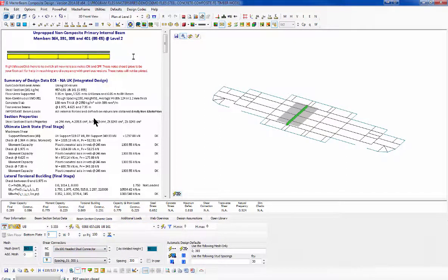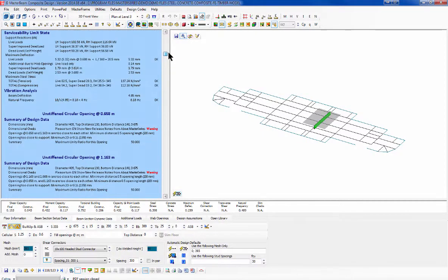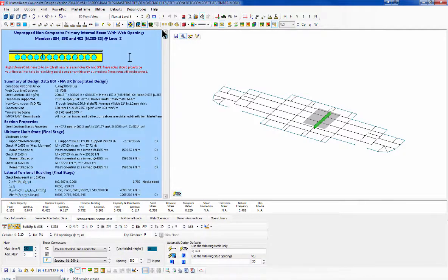So we've designed that one. I think over here we had a plate girder, and again we're just getting some problems with the two openings that are too close to each other around these holes. So we'd need to go back into the master frame and actually fill in the openings, because you don't normally have an opening right beside a beam coming in, so you really should be filling in those two openings, or moving your openings about to actually make that work.